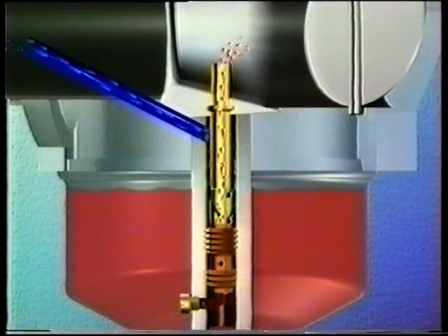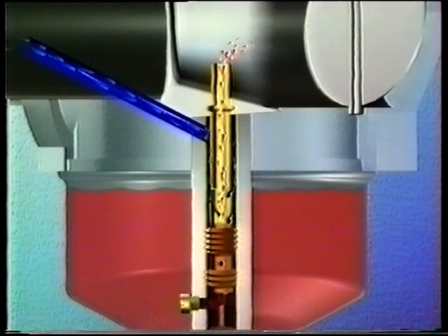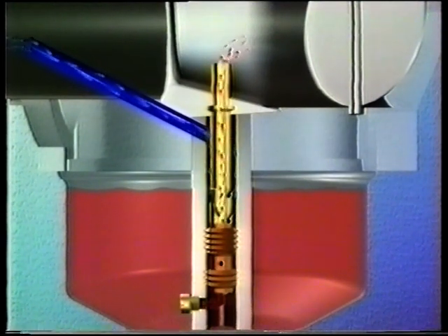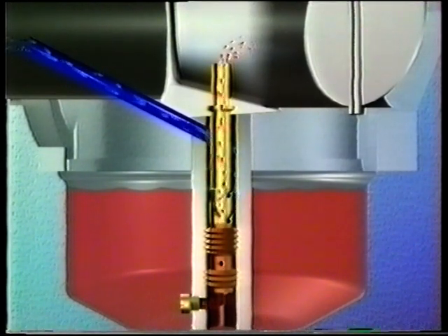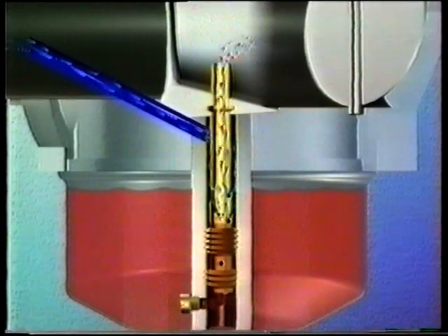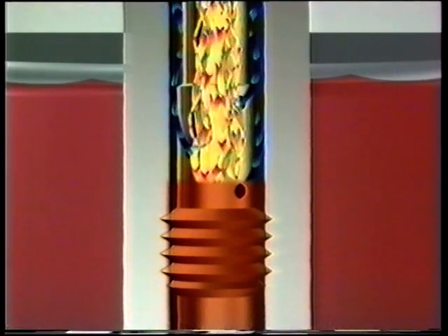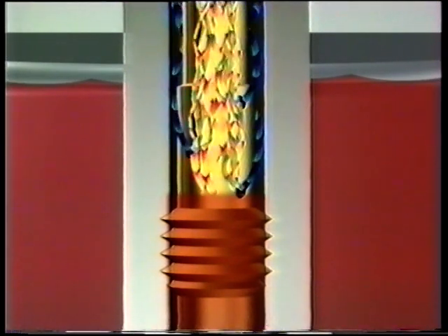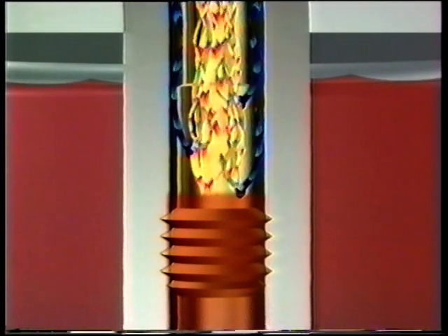The air bleed acts a lot like a bowl vent. It allows atmospheric pressure to act on the fuel in the emulsion well. With sustained pressure and airflow into the emulsion tube, fuel and air are forced up the tube and into the venturi. As the fuel level decreases, it exposes holes in the emulsion tube to the air entering from the air bleed. This allows more pathways for the air to get into the tube and start mixing, which speeds up the vaporization process and helps the engine run more efficiently.